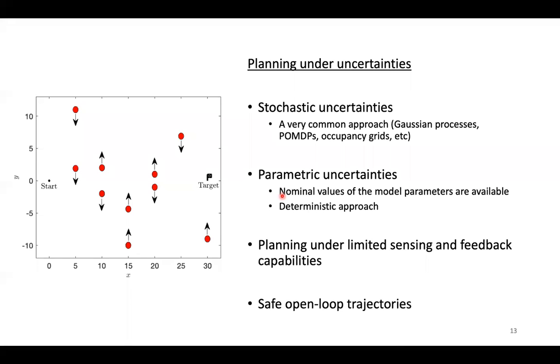So in the past, we had discussed feedback control, but in most cases, if the uncertainties are really bad, feedback control can only do so much. Regardless of how bad your uncertainties are, a feedback controller typically has some limitation. You can have input saturations, or you can have a really high amount of feedback that could be detrimental to the system.